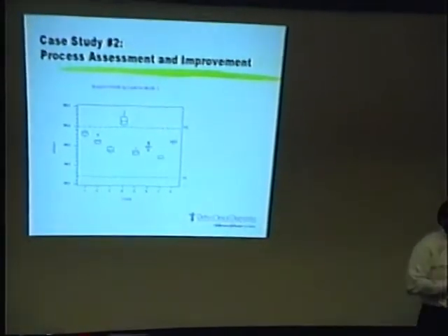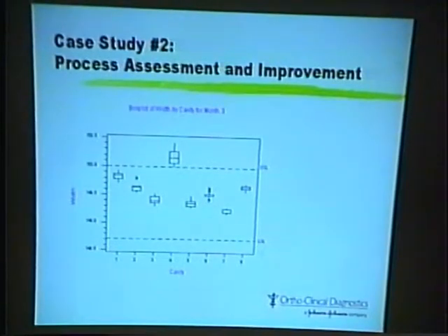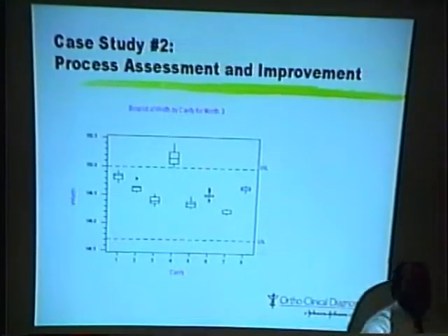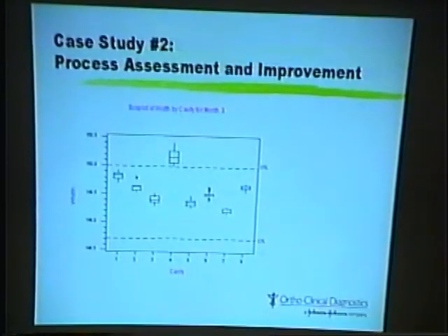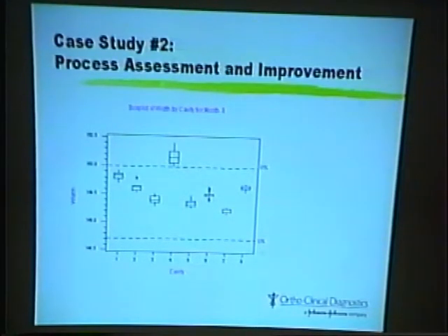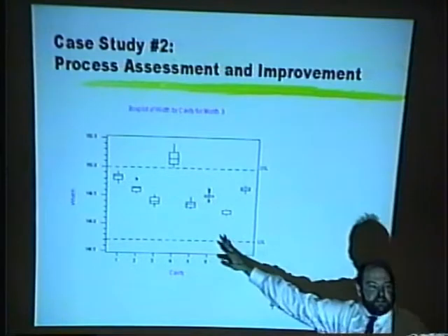What do you think? It's pretty obvious. Again, we're exploring, looking for explanations and ways to summarize the data. But we've definitely got differences from cavity to cavity. And that, by the way, is normal in manufacturing. It's very rare to build a tool that makes multiple parts at once where every cavity is exactly the same. We accept that. The only issue is how close they have to be, and is it acceptable? In this case, obviously, this is not acceptable.